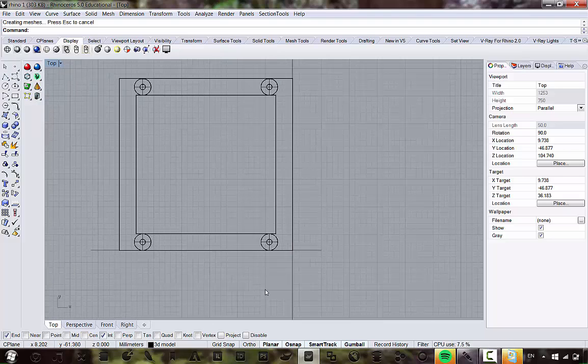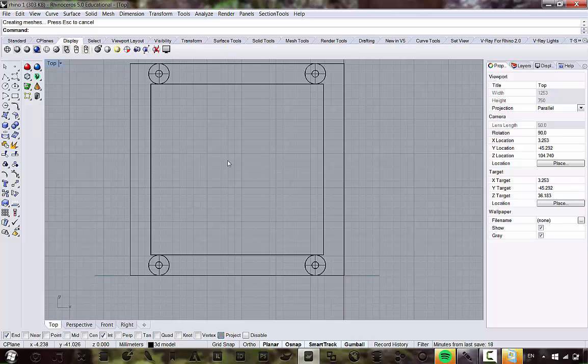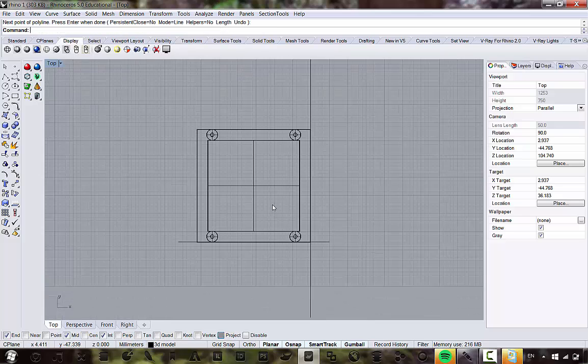So under here, I'm going to take the Project command. Again, Planar, turn that on so we know we're on the XY plane here. And I'm just going to make some cross bracing. So we want to snap to Mid in this case. So Mid on, snap to mid, drag it across. This is just a polyline. Snap to mid, drag it across, snap again.